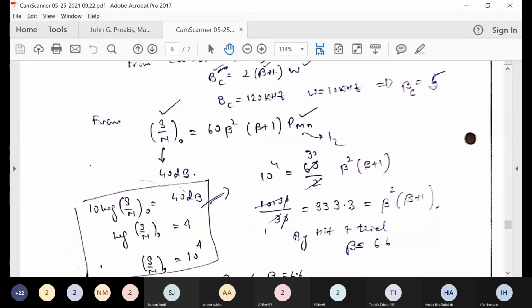And if I go less than 5, then I will be requiring more transmit power, while I want the minimum value of the transmit power. So I will compromise and I will use beta equal to 5, which is less than the threshold and which is the maximum possible value that I can go under the bandwidth constraints. Alright.